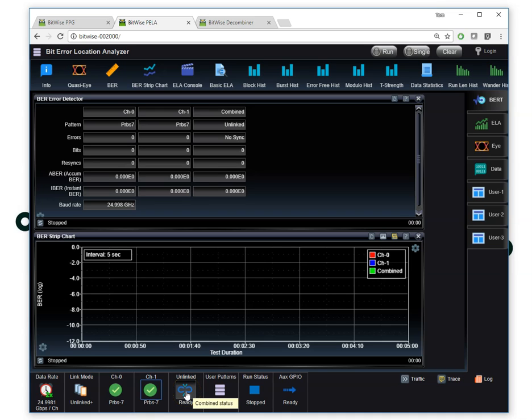Now this brings up an interesting point. If you have cables of different length and you were counting on these being exactly bit interleaved, that might fall apart. You might not be able to gain sync in an interleaved way. For that reason, we've included a small plus or minus 64-bit barrel shifting feature in the input of the PELA error analyzer. So it will shift through and find the bit position where sync is established. It'll display how many shifts it made to get sync. You can lock that down if you want to force it for future tests, or you can just allow it always to search through.